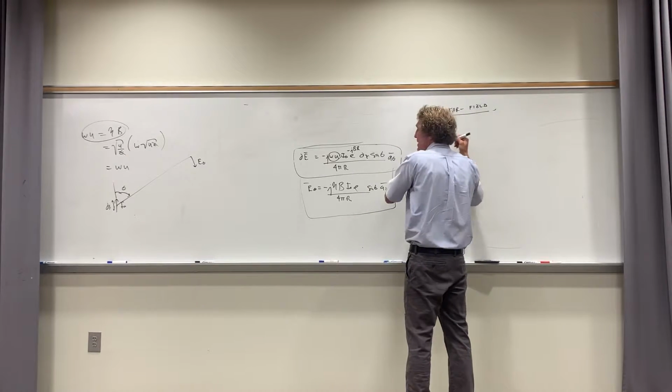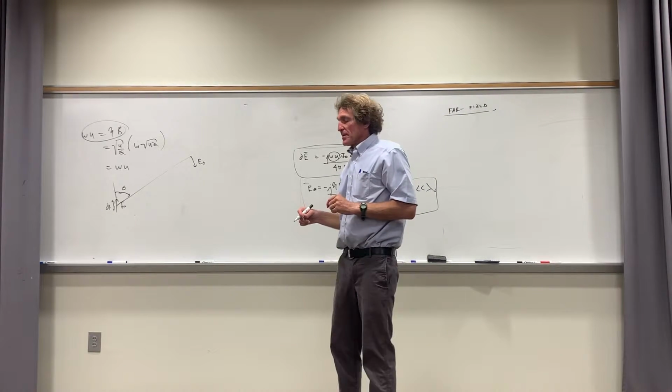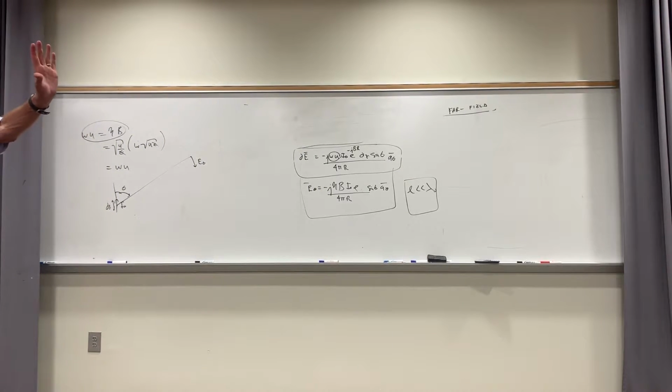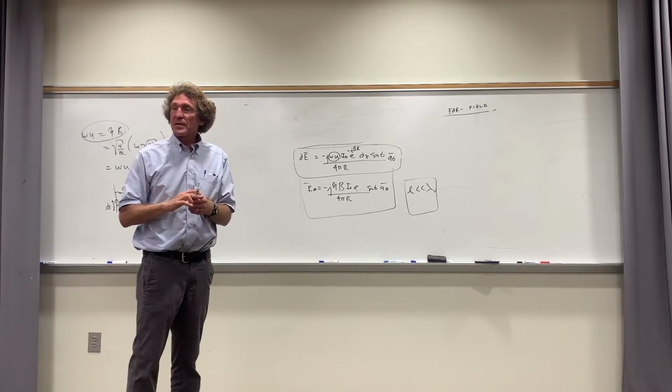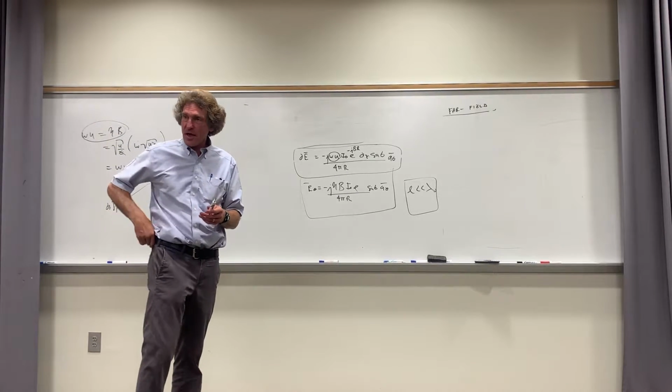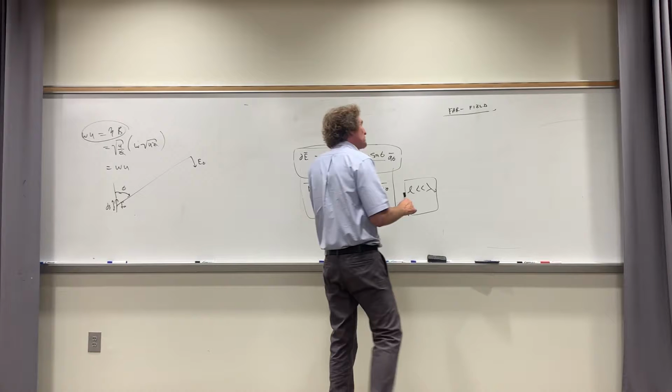Something happens. Far field means, there's a lot of definitions to it, but here's the one that works all the time. I'm far enough away so that the electrostatic energy or magnetostatic energy, the magnetic fields or electric fields due to the static or DC currents, are now of no consequence. I'm far enough away, and you don't need to get very far. So now, if I'm in the far field, this is where all the energy is launched at that point. I'll get down to the specific definitions of how far you have to be for the far field in a bit. But for now, I'll just put down far field.